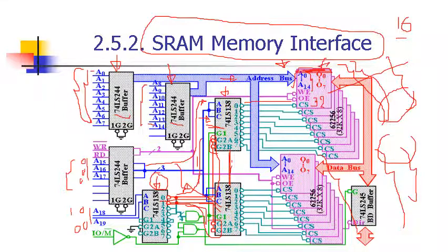I guess you can easily now follow the given connections and make sure that the design is made as required, connecting 512 kilobytes of static RAM to your system through 16 different chips, each of 32 KB.